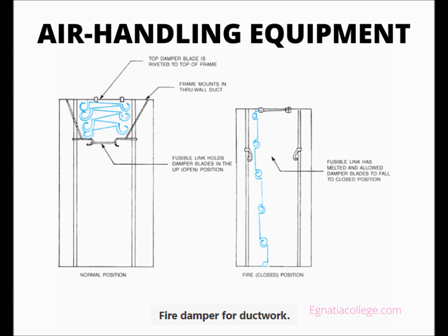At the second floor it is joined by the exhaust air from the second floor janitor's closet. On the second floor plan there is also a symbol indicating a fire damper designated as W access door at floor. This damper, a metal gate, closes off the duct if it gets hot in a fire. This is necessary because the building code requires fire-rated construction, and an open duct is a great place for fire to spread. The access door at the floor allows for maintenance and repairs to the damper. Notes at both levels indicate that the duct between floors is 6x6.